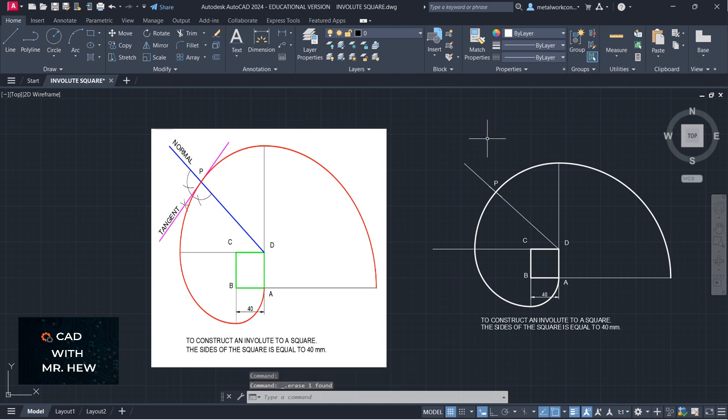This line is not part of the construction. All right, so I'm going to go single line text. I'm going to turn off object snap and select right here. The height will be 6, press enter. Rotational angle looks like 120. So I'm going to label it now: normal.